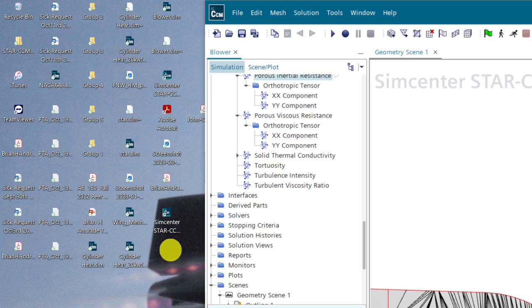But we tend to not want to set values to infinity. That generally makes computers unhappy with us. So we don't. What we tend to do in the case of fins, if these are not equal, is that we will say that the X direction resistance is equal to, it depends on what you're doing, honestly, but as an approximation, you say 100 times the resistance in the Y direction. Technically, the simulation will let flow across one of these fins, but it will be really hard for it to do, and it will lose a lot of pressure doing it. So the flow will almost always align exactly with those fins.